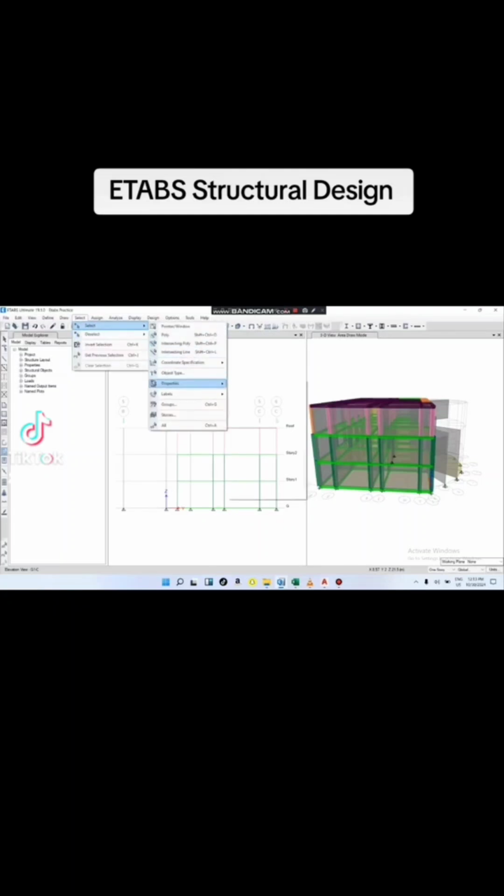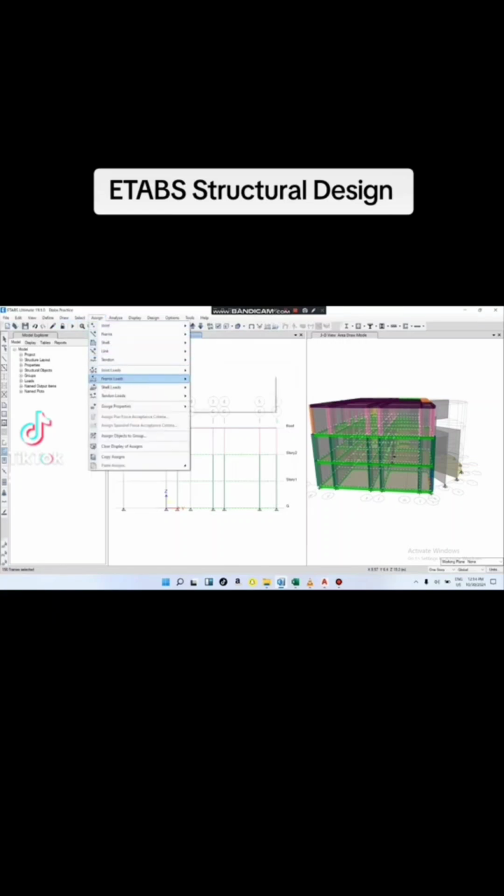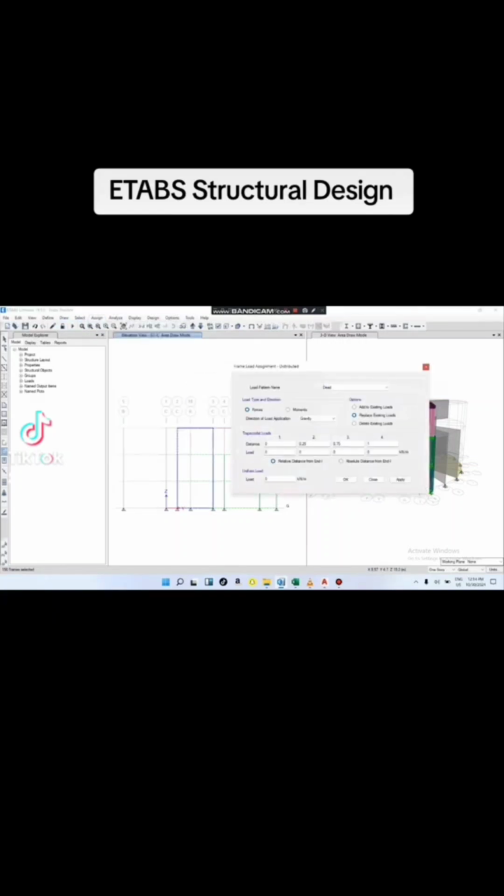So we go to the frame, select frame section, and I will choose from the ground to the second story, which is typical, so I will say ground floor beam or first floor beam, any one I click on, it will be the same. Now it selected the 3 stories: the ground, story 1, story 2.